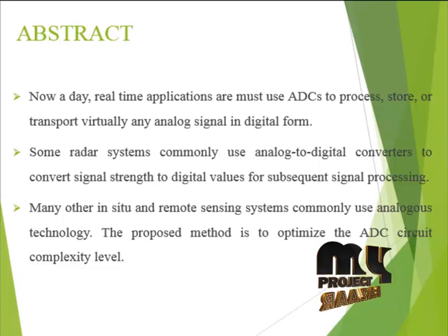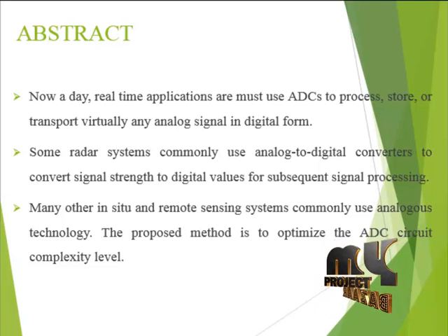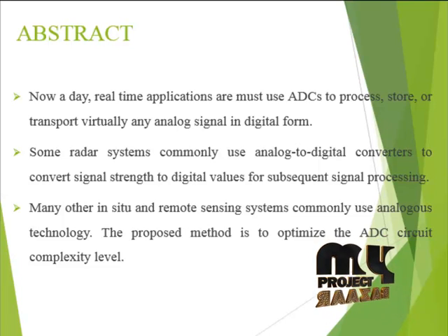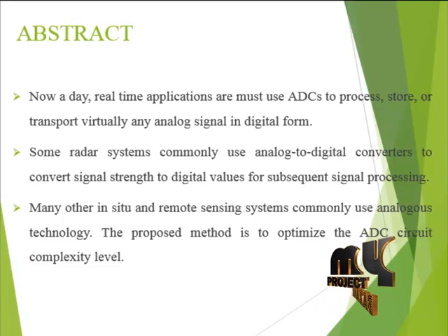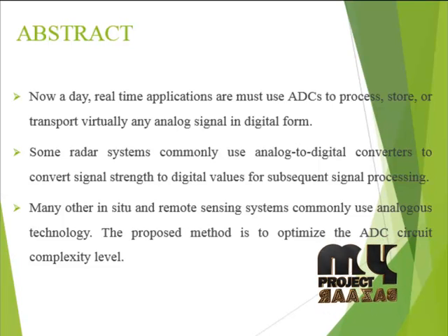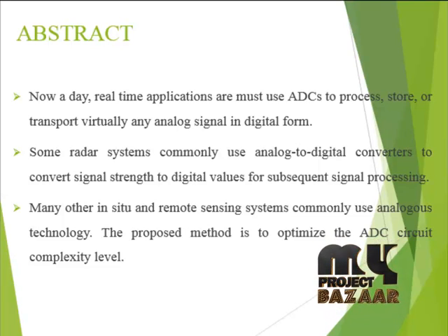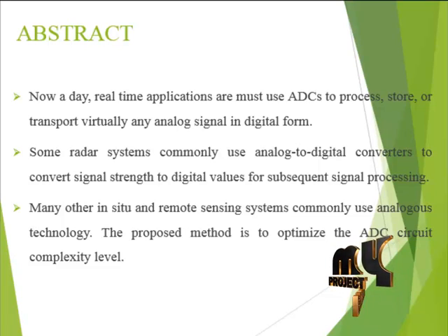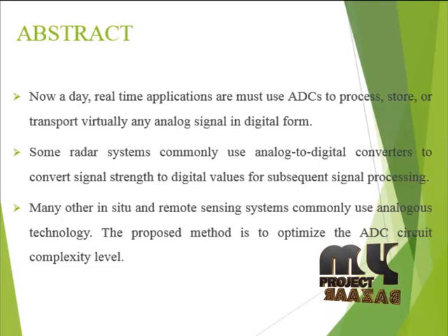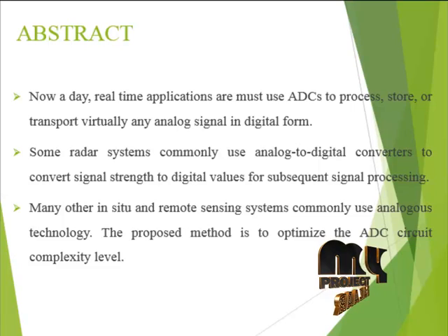due to the low device gain and reduced headroom. The traditional approach of cascode amplifiers to generate sufficient gain is limited by the CMOS process. Although we still require large power and complicated frequency compensation techniques, we have achieved a high effective gain with a low gain op-amp. We have also considered correlated level shifting and parallel use of amplifiers.